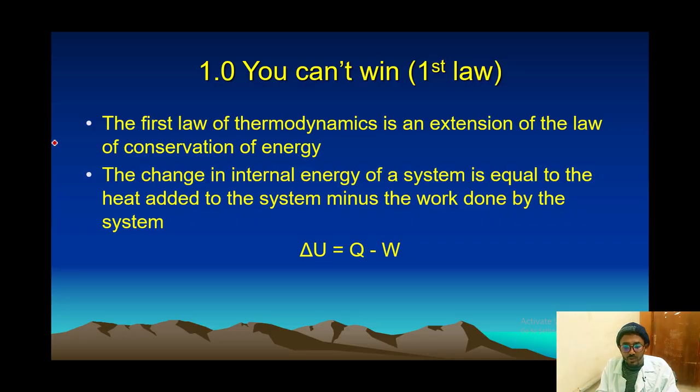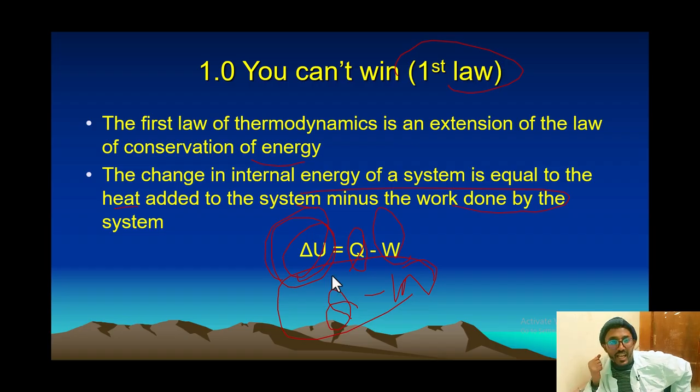Now this one is the concept of the First Law, you can win. So what is this all about? The First Law of Thermodynamics is an extension of the law of conservation of energy. The change in internal energy of a system is equal to the heat added to the system minus the work done by the system. So we have the heat added to the system, Q, and also the work done by the system, W. The difference between those two things is the change in internal energy: the heat added to the system minus the work done by the system.